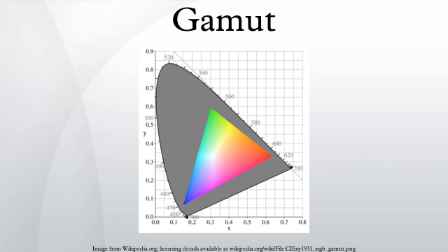Photographic film can reproduce a larger color gamut than typical television, computer, or home video systems. CRT and similar video displays have a roughly triangular color gamut which covers a significant portion of the visible color space. In CRTs, the limitations are due to the phosphors in the screen which produce red, green, and blue light.